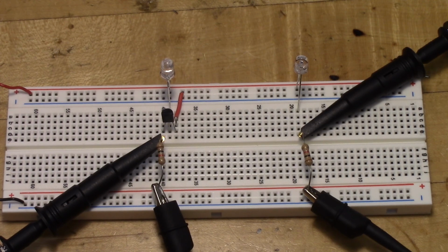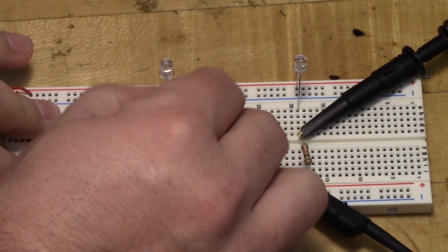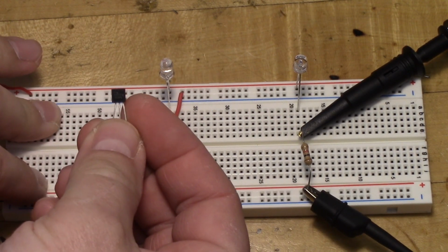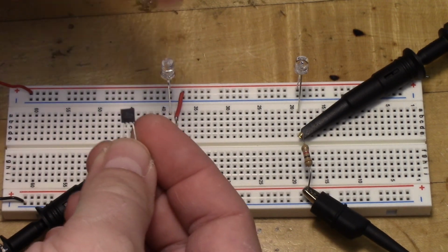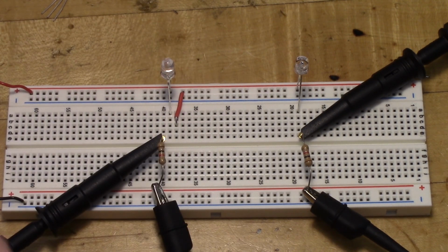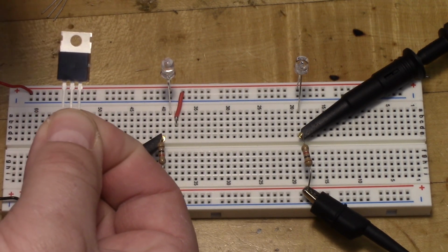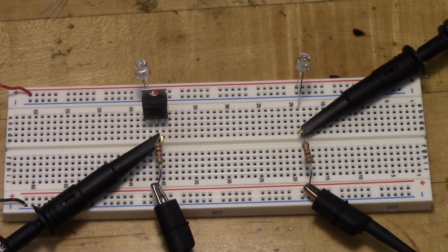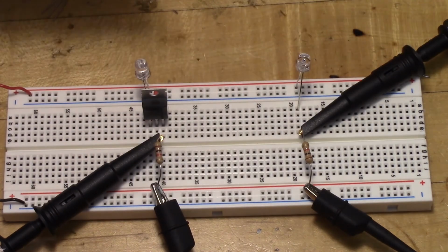And of course, I turn the power off first. The NPN 2N2222 pinout is emitter, base, collector. Now, they just have to be different. The TIP122 is base, collector, emitter. So, turn the power back on. Now we'll be able to see that the